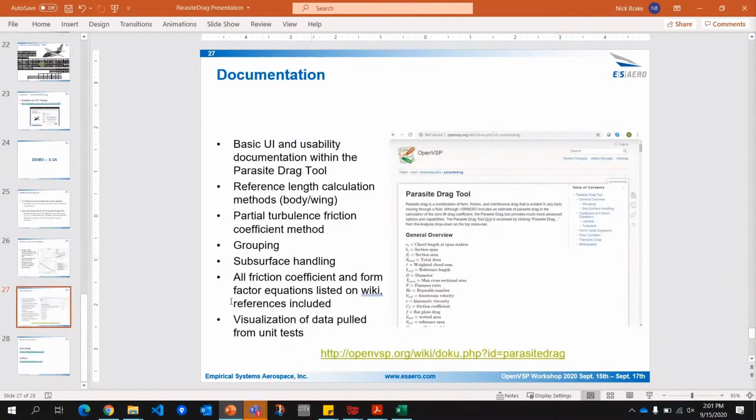For wings, and also for rotating propellers and rotors, it treats the wing in a stripwise manner, calculating the local velocity, the local Reynolds number, and applying a simple, it amounts to a form factor, but it's essentially data based on an NACA 0012 out of Theory of Wing Sections. For a full airplane, I think it's reasonable to say you could just ignore the Parasite drag out of VSPAERO and use the Parasite drag buildup instead.